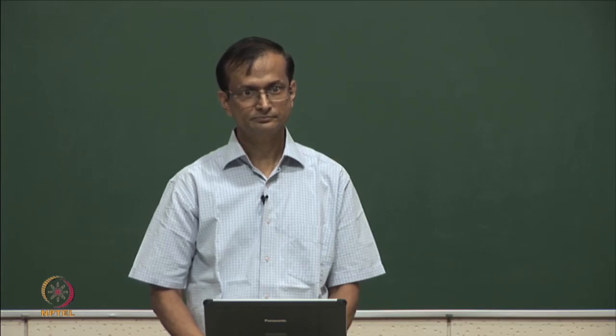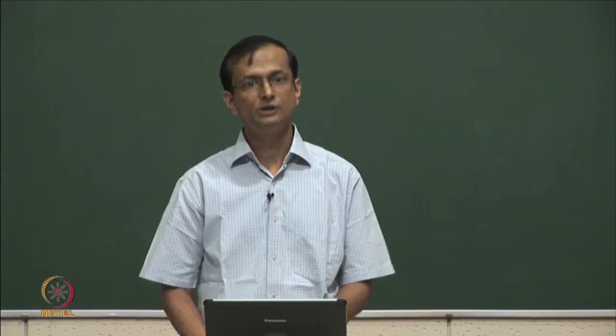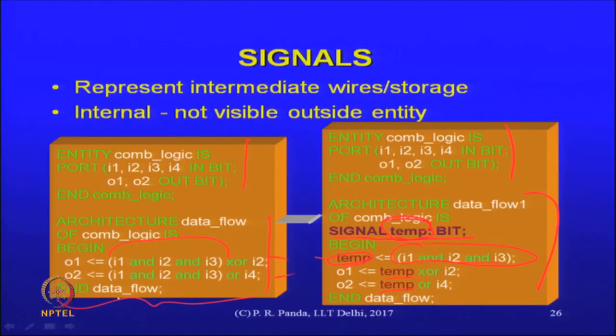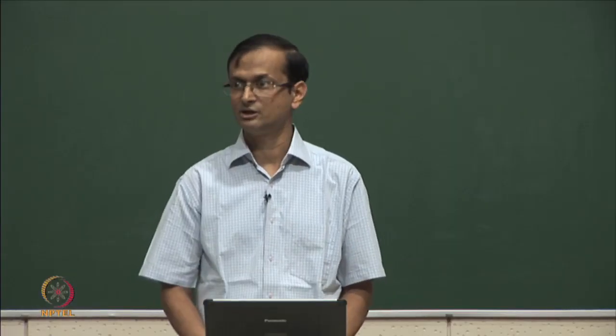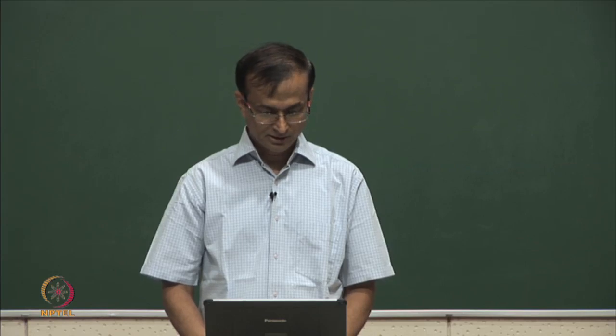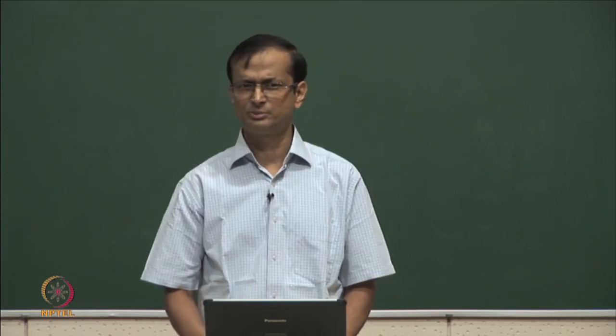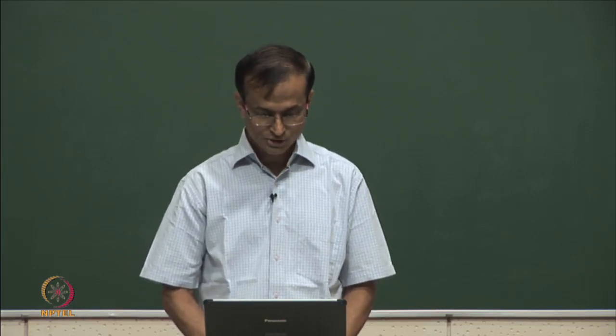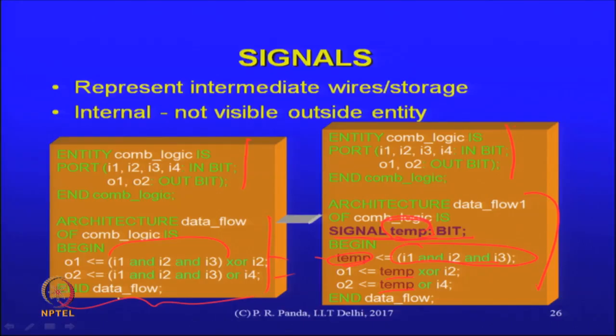You can duplicate the two AND operations there and create 3 input AND gates. So, I have some redundancy in the original specification that I have manually optimized in that second specification. Your question is, are the synthesis tools smart enough to see that themselves instead of asking us to manually identify that something is common? Here it was obvious, sometimes it might not be that obvious. Remember, you might have specified it in some other set of operations, it might still be a 3 input AND gate. Are the synthesis tools clever enough to detect that themselves?